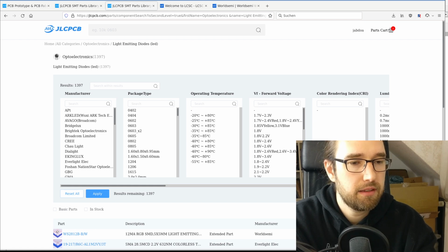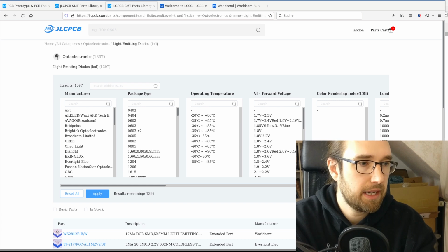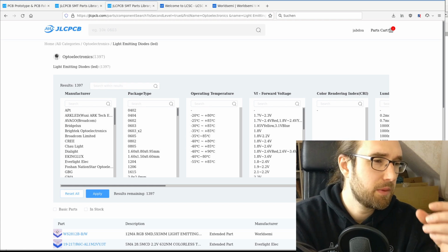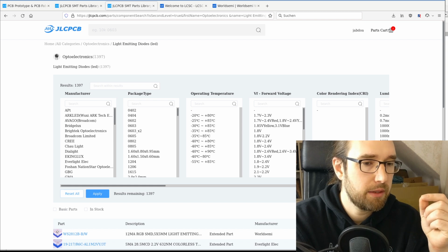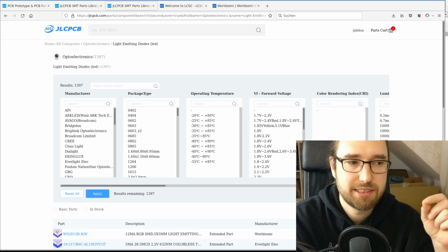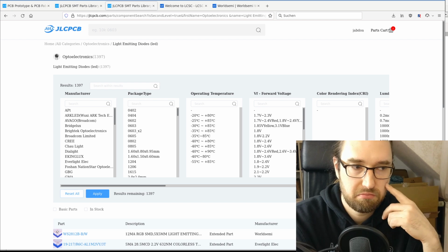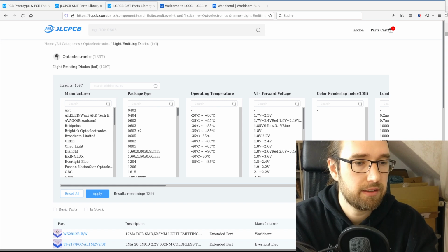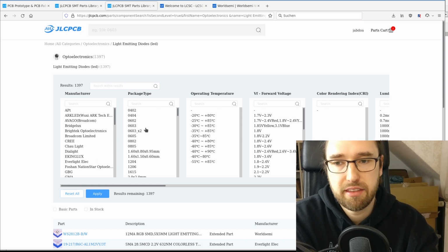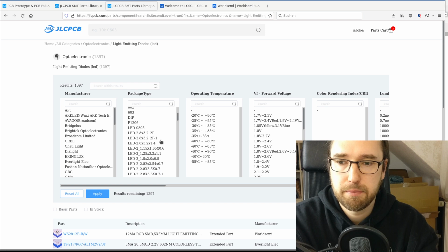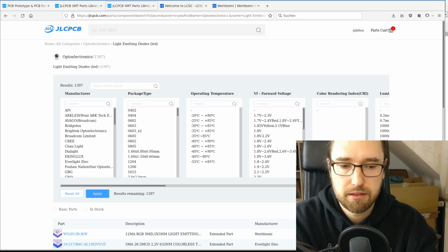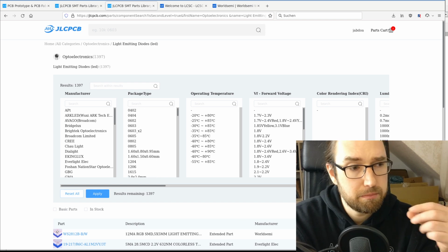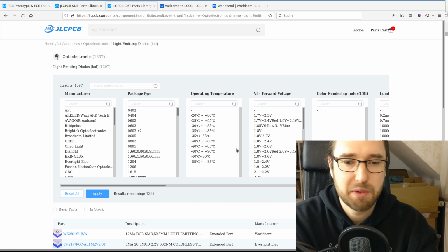Right. APA102 is SPI based. Basically what Stern does, I mean, they do not use APA102, but I guess you could simply put them on a Spike board and they probably will work. So you shift out using the SPI protocol, and OPP can do it. I think Spike can do it, but others might as well. It's simple. With MPF you can bit bang it, but it won't look well. It will look pretty basic in most cases.